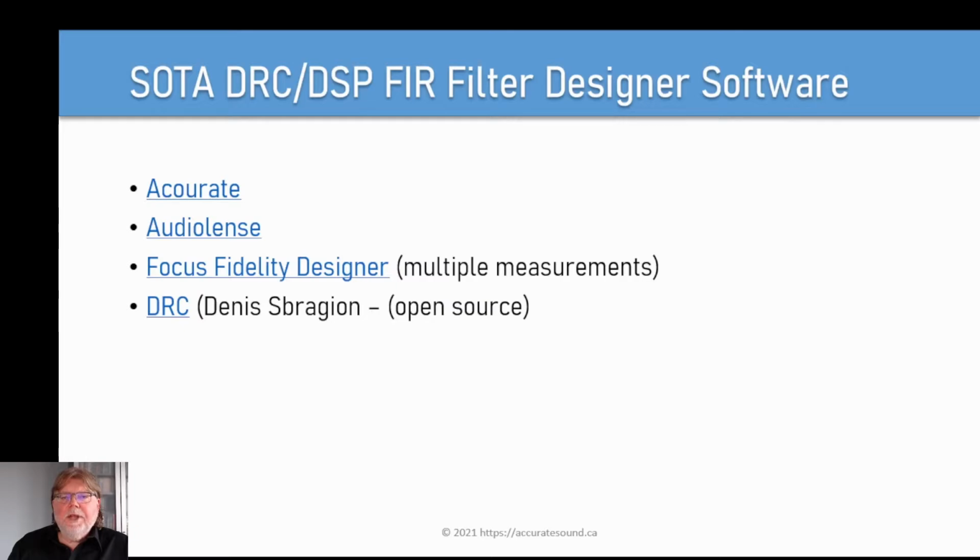If there are popular names missing, it is because for one reason or another, or many, the DRC software cannot create a proper transfer function to restore the ideal minimum phase response. I should note I have not reviewed all DSP DRC software, so there is a possibility that there are more out there, and I would be looking for psychoacoustic filtering and frequency-dependent windowing capabilities as the minimum entry level. If the DRC DSP can't do that, then it's not a contender for state-of-the-art room correction.